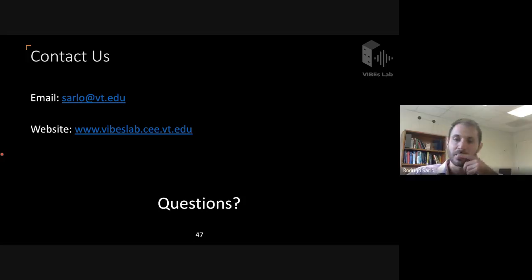Yeah, and in fact, as we were working on this, I thought the next step would be to run this on the long-term data set and see how well it deals with these fluctuations. So that's something that we're working on, and we're interested in seeing if the dynamic baseline approach can capture recurring baselines, if you will. So when the bridge returns to a certain condition, we understand that it was there previously, and try to use that as information for understanding environmental fluctuations versus damage, which isn't necessarily returning to the original state.